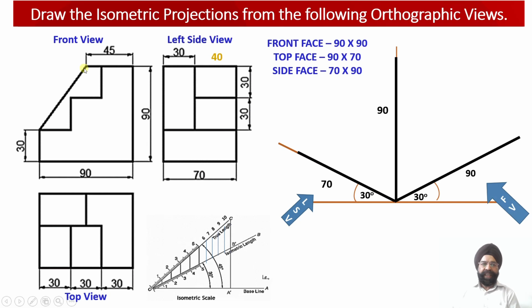and then this web will be moving down, inclined towards the bottom step, that is towards the top of step 1. So this web, which has a thickness of 30 millimeter, that is the width equal to 30 millimeter, will be moving down from this point, which is at a distance of 45 millimeter from the rear back side face of this particular solid.